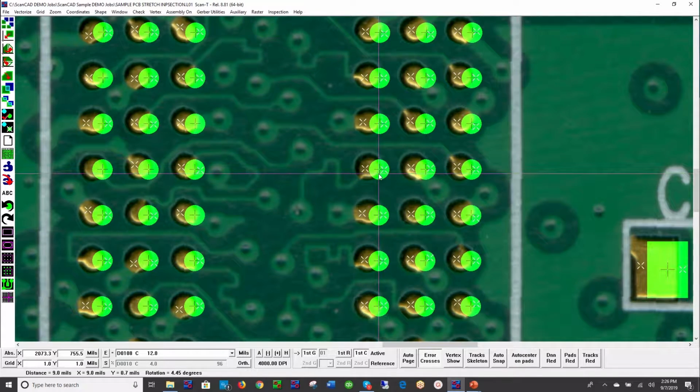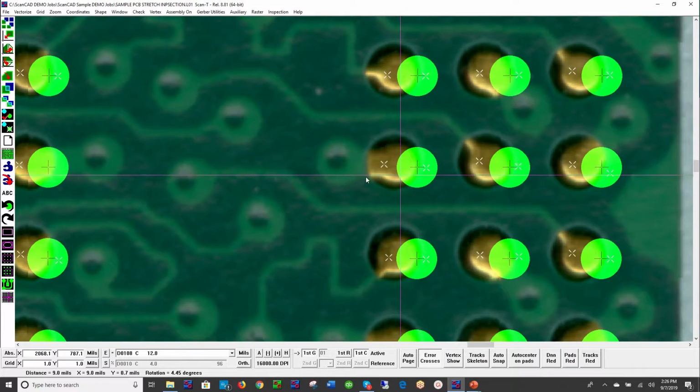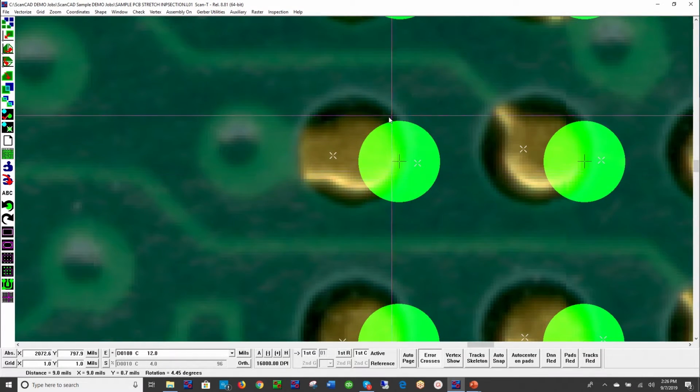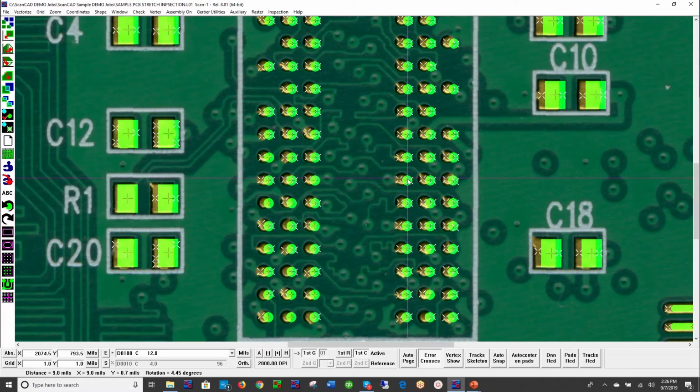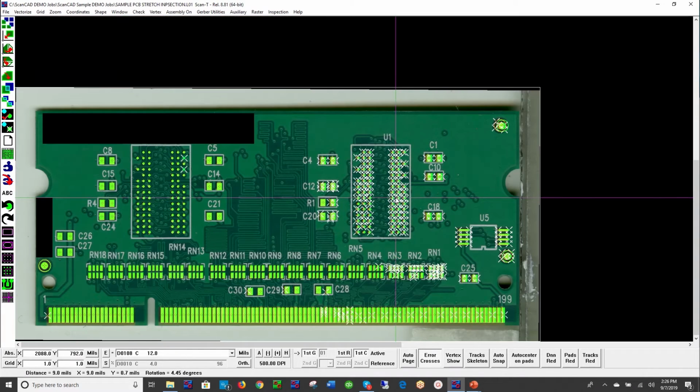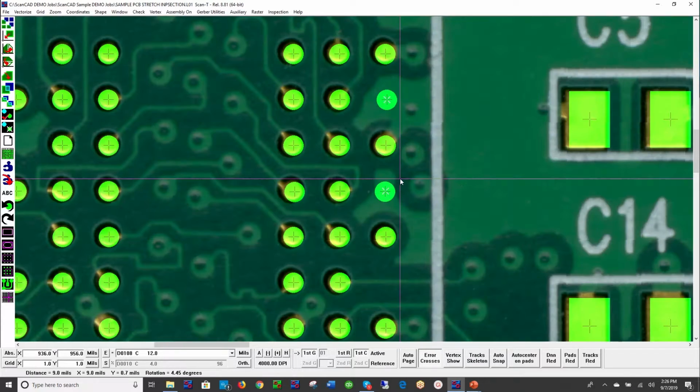If you use this green data to manufacture a stencil, to print conductive material onto these gold pads right here, you can see we would have a very serious production problem. And we'll talk more about that in a minute with a Motorola study that was done with this technology. So I just wanted to give you a quick example of what that inspection might look like. There's an alignment error. We also have another error happening here.